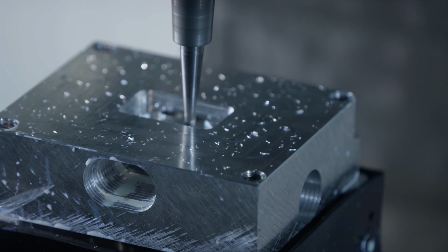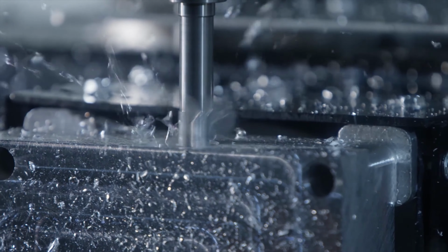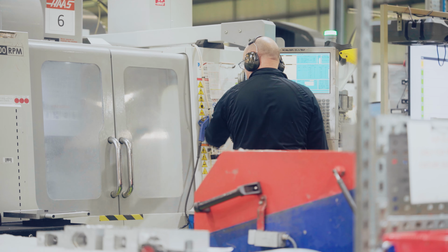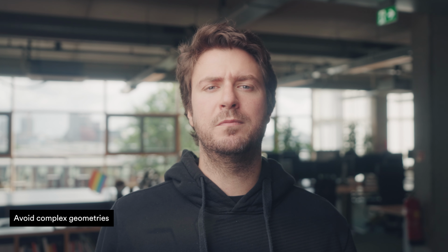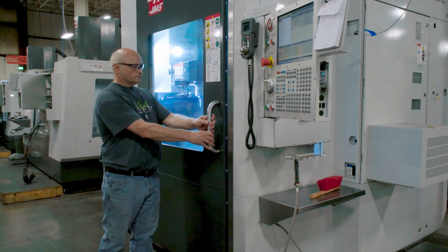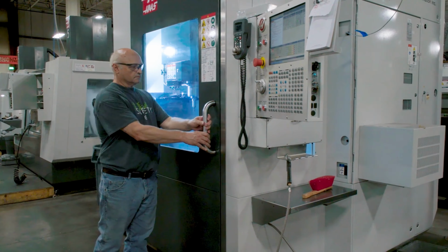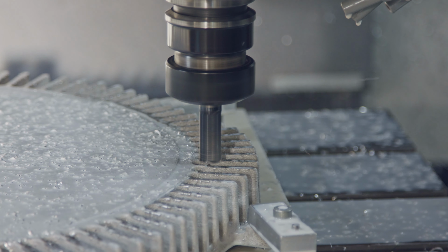Simplifying geometry in your design is crucial for making the manufacturing process easier, faster, and more cost-effective. First of all, avoid complex shapes. This is because complex shapes often require specialized tooling and multiple manufacturing steps. This increases production time and cost, and they can also lead to higher rates of defects due to difficulty in maintaining precision during machining. In order to fix that, you can segment complex designs.